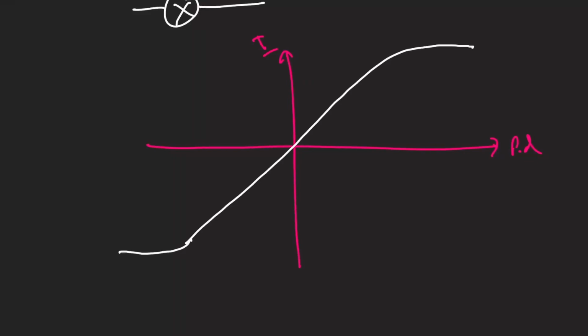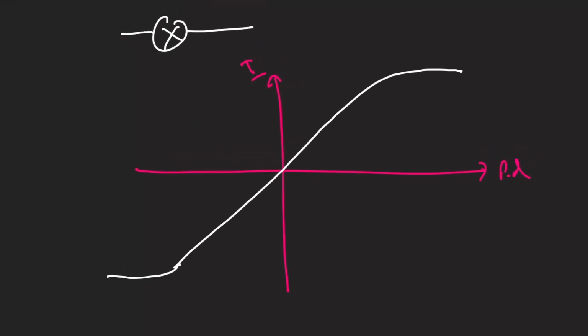Okay, so what's happening here is that you can see the lamp behaves like an ohmic conductor for a lot of the time. All of this section is a straight line, therefore the gradient is constant, therefore your I over V or your V over I is constant, therefore your resistance is constant. Anything with constant resistance is an ohmic conductor. Then when you get to very high potential differences, even when it's very high and negative, it's still a very large potential difference or a very large current. At this point the filament lamp starts to heat up. When it heats up, the resistance actually increases, and so you end up getting a much less steep line over here.